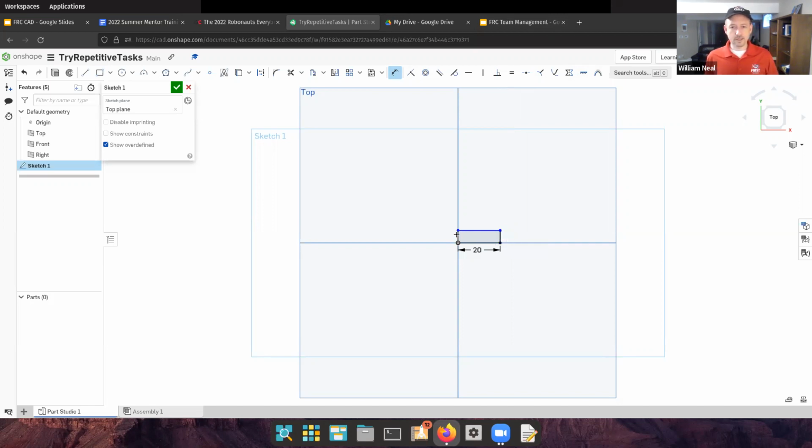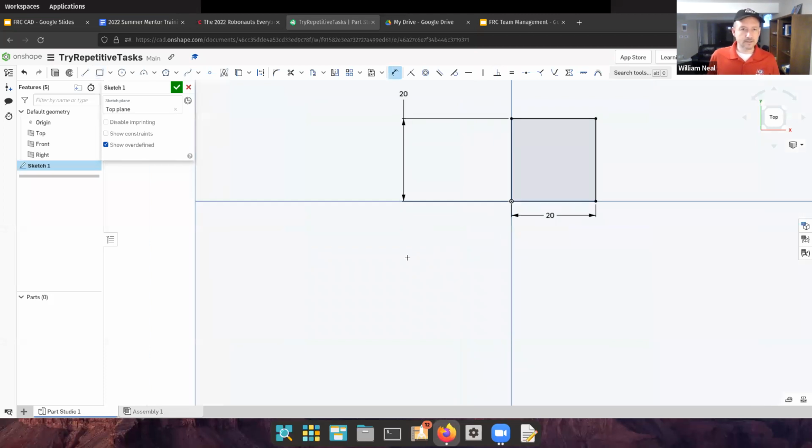And I can put a constraint here to 20 millimeters. There we are. Okay, now I can start drawing this feature here. It starts on the line, does something like this. I'm being a little bit easygoing as I make my sketch. It's very approximate because I can constrain it now. For example, that's kind of off, but I want it to be vertical. So I'll just click on this one. Now it's vertical. This one also should be vertical.